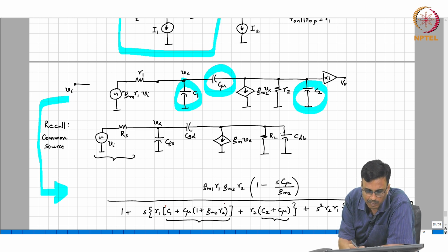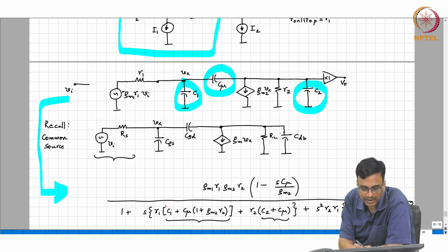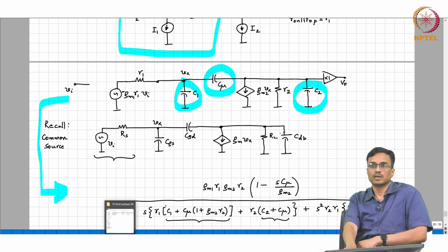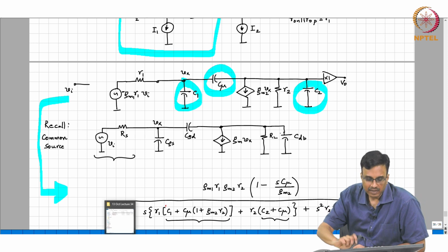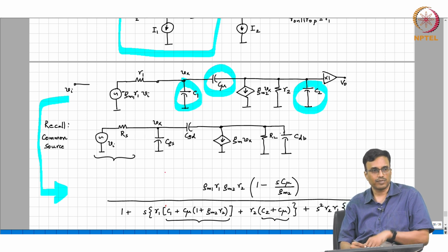So this term will become, what do you call the time constant, will increase by R1 times Cx that you add, whereas if you add it in parallel with C mu, the effect of C mu is getting electronically multiplied due to the Miller effect, right.